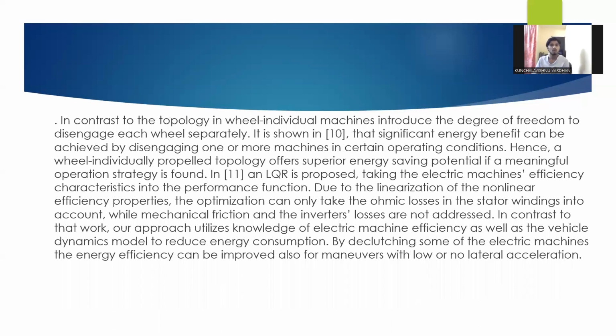In contrast to the topology with a differential, wheel individual machines introduce the degree of freedom to disengage each wheel separately. It is shown that significant energy benefit can be achieved by disengaging one or more machines in certain operating conditions. Hence, a wheel individually propelled topology offers superior energy saving potential if a meaningful operation strategy is found. An LQR is proposed, taking the electric machine efficiency characteristics into the performance function.